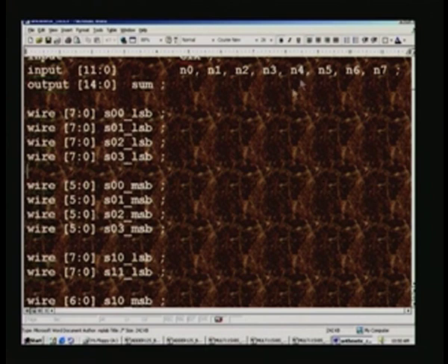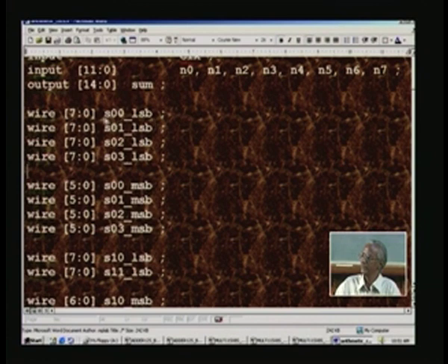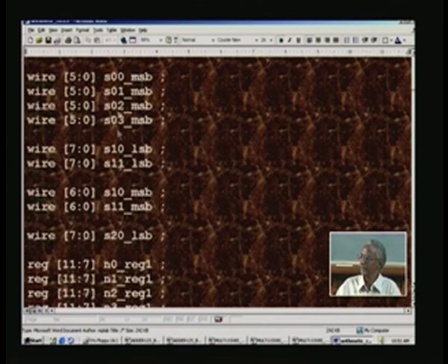So during the course of the other statements that we will actually work out the arithmetic portion, we will be encountering very many intermediate signals. Some of them may be with assign statements, and therefore they are all declared as wire, and the width of each is also declared here. For example, we will be adding LSB as we had mentioned in the pipeline partition earlier, and we will also be adding MSB with the carry of the LSB addition and so on, and they all have to be declared here.